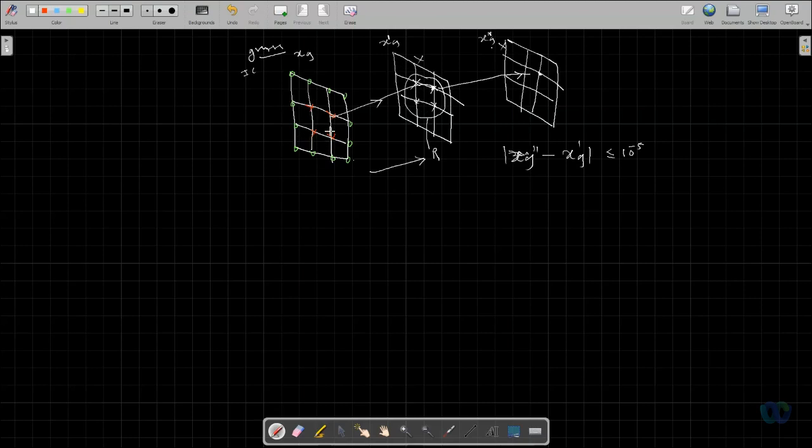For unsteady problems, it's okay, but for steady problems, how will we solve them? This is called the false transient approach. We move in time and then we keep on checking. This is called iteration. There we would say time stepping. Now this is the first iteration. In the first iteration, we guess the value and find the appropriate values. Then we do the next iteration and find other appropriate values. But within that iteration itself, we have to find all the interior points and boundary points in such a way that the residual of the corresponding equation falls to 0.